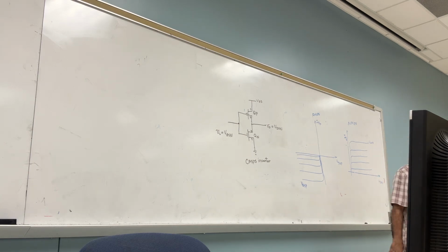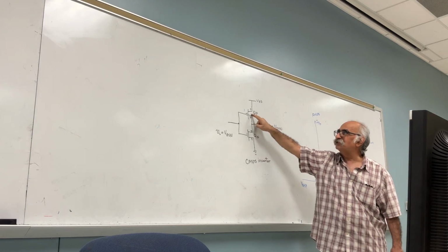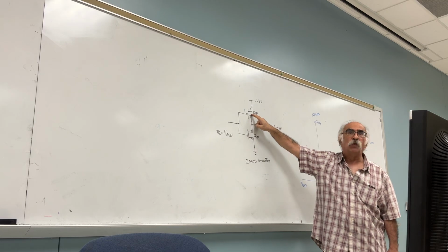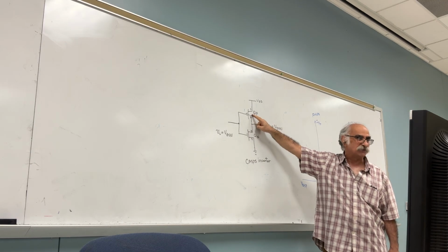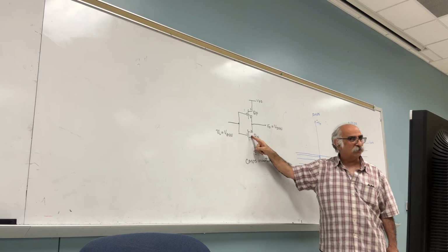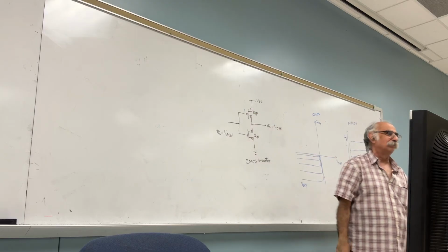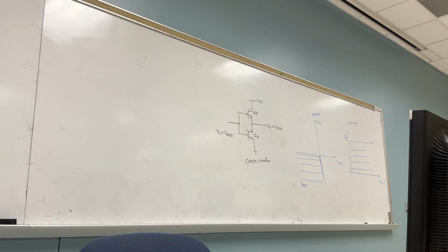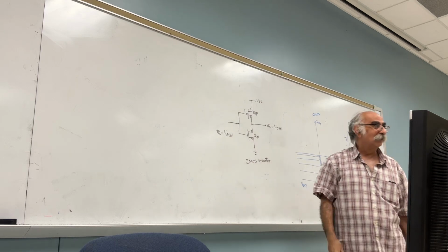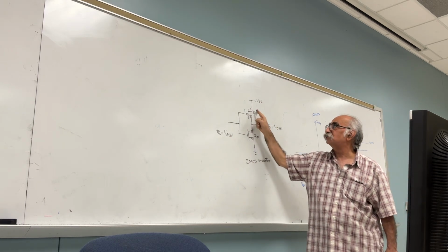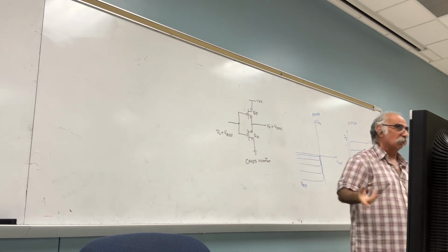Remember, by the way, in the resistively loaded CMOS, the load line was a straight line. Remember the straight line? This one is not going to be a straight line. Let's understand. I replace the resistor by a PMOS. That's a PMOS replacing the resistor. I'm going to assume that this is the driver transistor, and this is the load. This one is going to supply this one. In other words, if you replace this resistor by this, you can assume that this is the load.